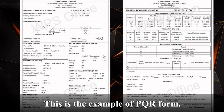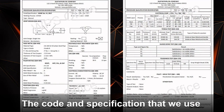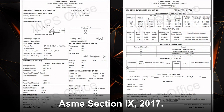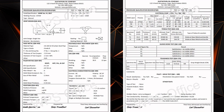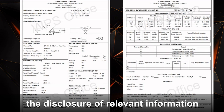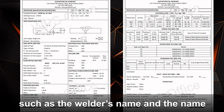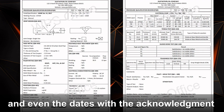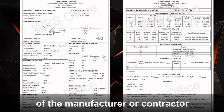This is an example of a PQR form. The code and specification that we use in this form or document is ASME Section 9, 2017. Another important component of the PQR is the disclosure of relevant information, such as the welder's name and the name of the person who did the inspection, and even the dates with the acknowledgement of the manufacturer or contractor.